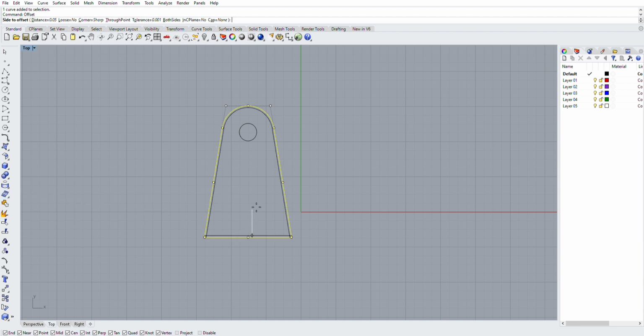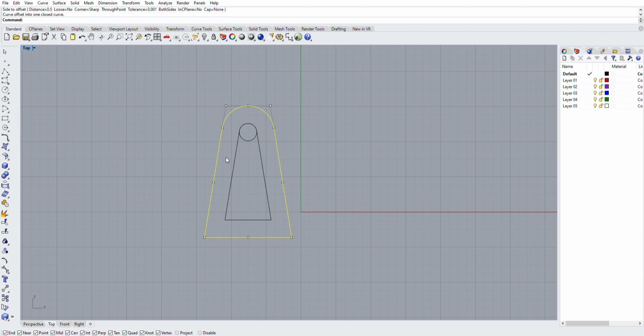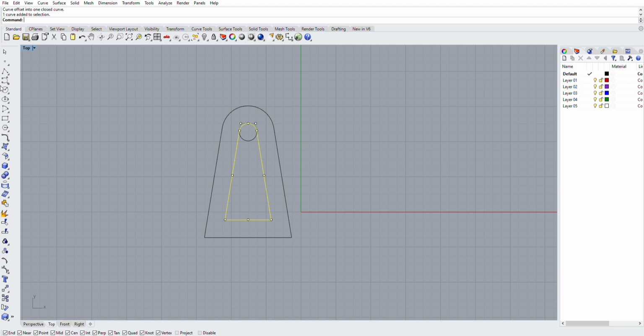Now, let's say we have this tab and we want a little bit more style. Nothing's faster than a hole. So we grab the offset command and we offset this tab in 1/2 inch. But if you can see, obviously that 1/2 inch in includes our hole, so we built another circle to give us our bushing space. Grab that circle, the offset dimension there, trim tool to remove it. We've got a windowed tab now. And if we go over to our fillet corner tool, we can set a radius, fillet the corners, and it looks like a finished tab.